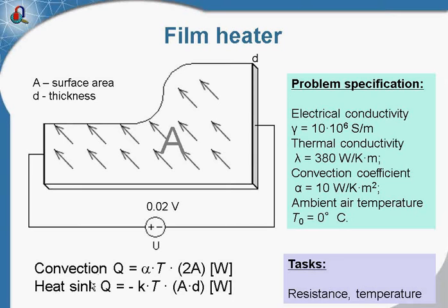And this is the heat sink, which could be not only the constant value, but could also be the function of the temperature. The volume heat sink. We can adjust the coefficient so that the volume heat sink will take the same value as the natural convection. So let me show you how this trick is done.